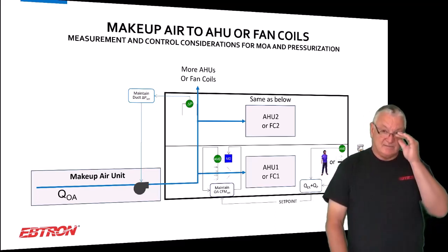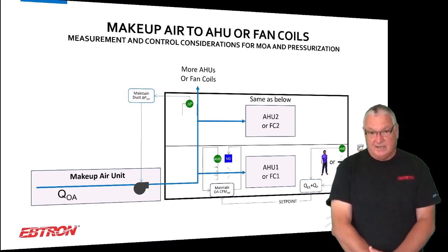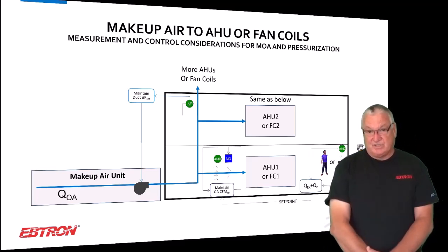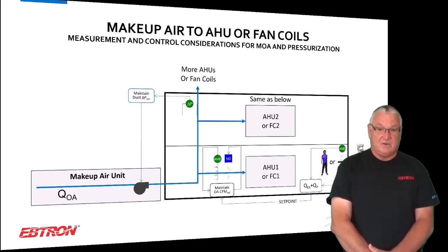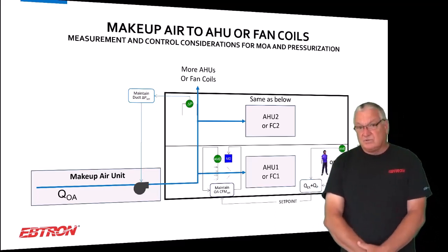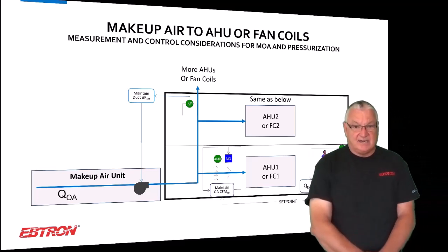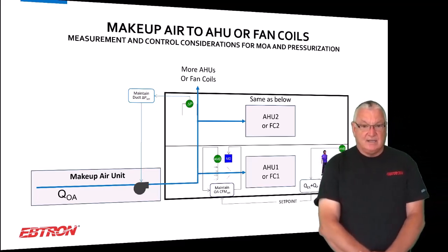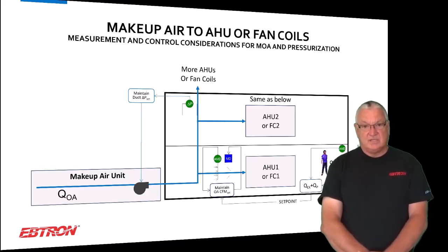Doesn't matter, the system's different, but we still have to bring it in. And a lot of times we'll see people just totally ignore the flow measurement into these fan coils, which are in a lot of cases variable speed fan coils, or variable speed air handlers, or doing DCV where the outside air set point varies, and it's like, you have no control of this.